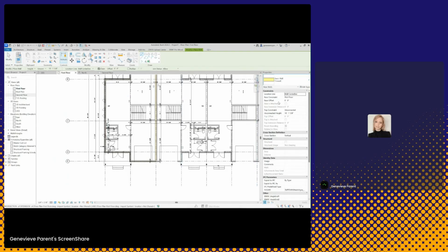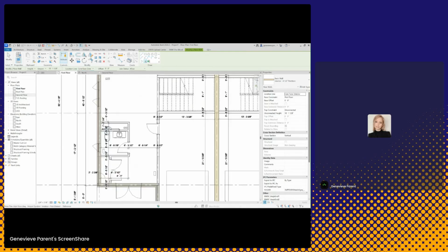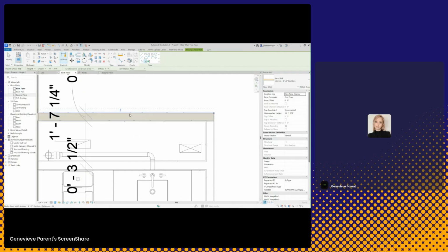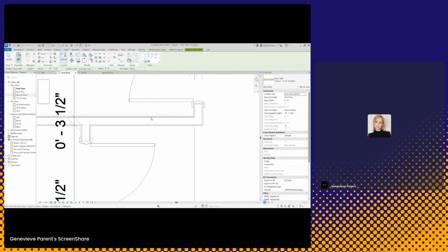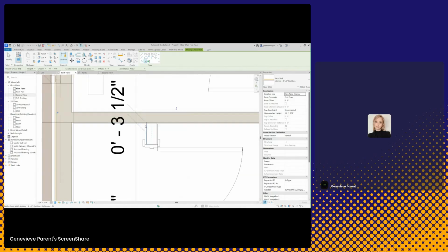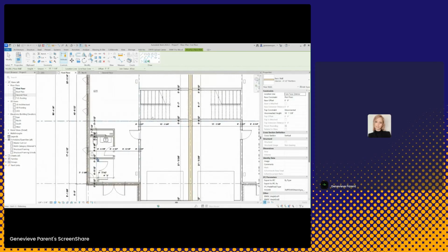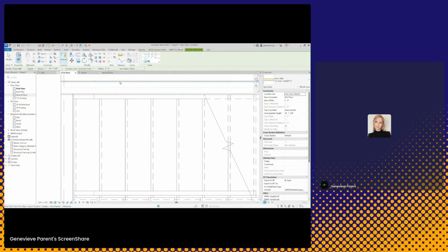Okay. I will need interior partition. In this case, I won't put it on wall center line. I will pick line, and I will do core face exterior, which is fine with me. And then I'll just go drop these walls in. I'm not worrying about closing them up right away. And these walls are different, so I do have walls for stairs. I'm good. I will put these in here.